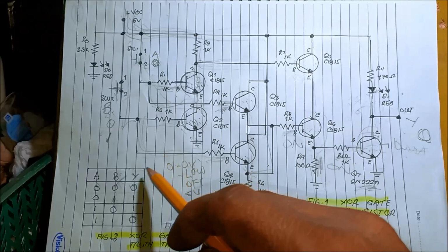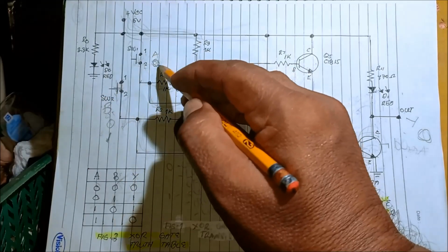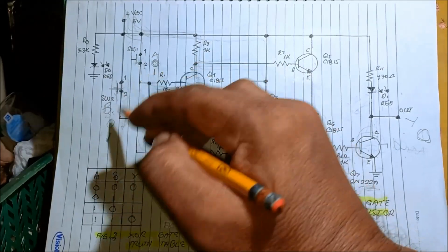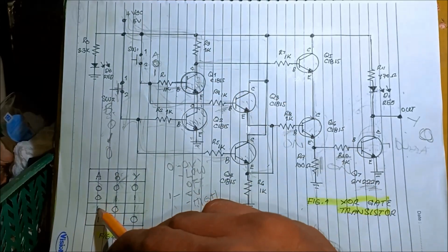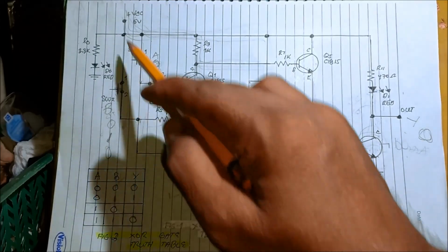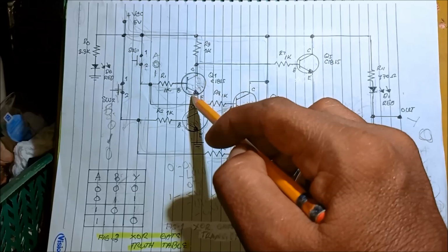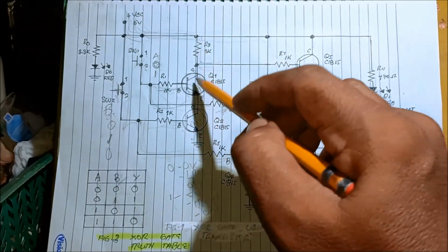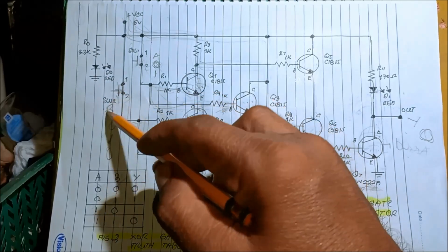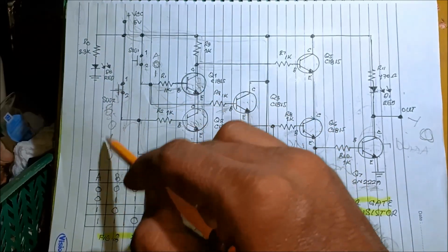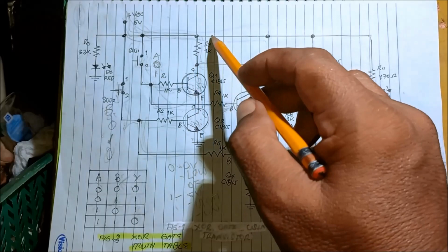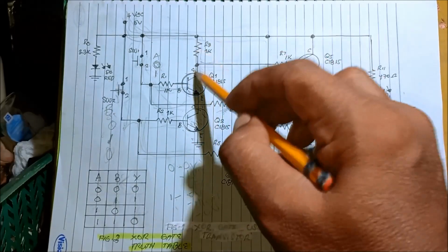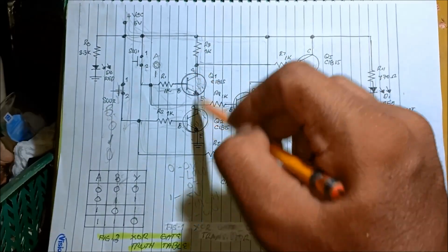And for the other transistor, if this is now 1 and this is now 0, switch on is 1, will make this transistor what do you think? It is still off because switch B is off, 0. The current will not flow into the collector to emitter then to the ground.